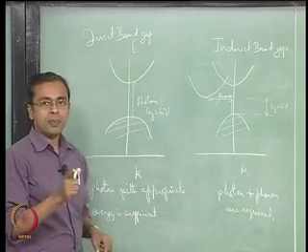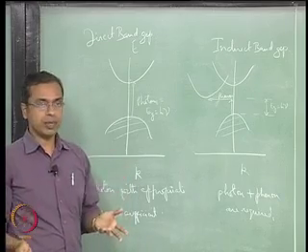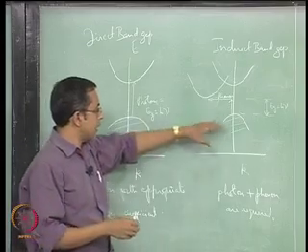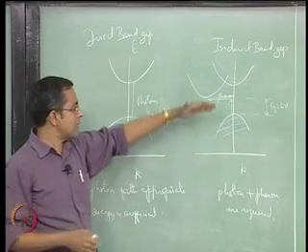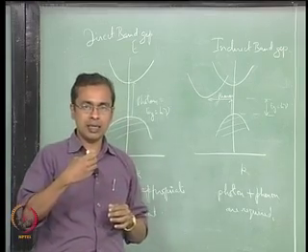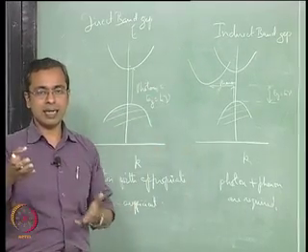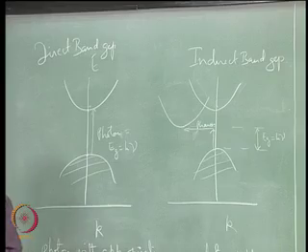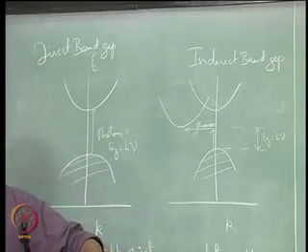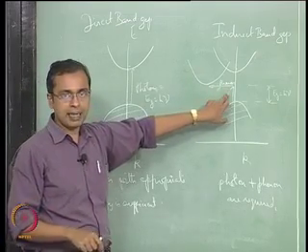As a result, for optical properties direct band gap semiconductors are much more effective than indirect band gap semiconductors. The number of times this transition occurs and similarly the number of times the transition backward occurs defines the amount of light you can get out of the system. So you have raised all the electrons, if they begin to fall back they release light, you see the light. The intensity of the light depends on how many of these electrons are going through the process. The energy of the light is defined by the band gap.